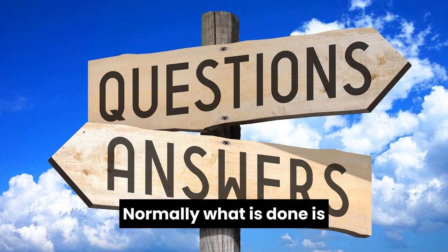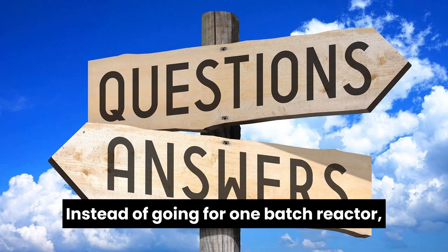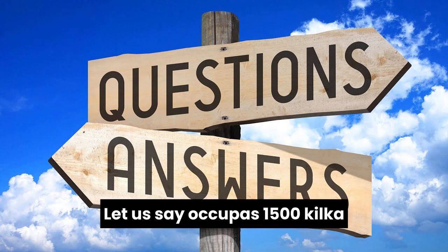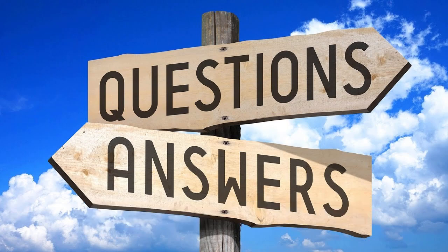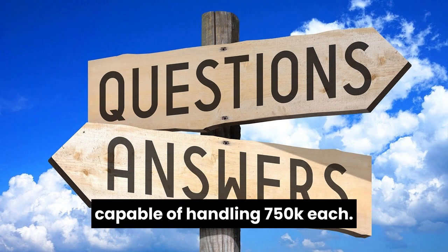Normally, what is done in large capacity STPs is that instead of going for one batch reactor, you have 2 parallel batch reactors. Let us say you have 1500 KL of wastewater per day to be treated. So instead of taking one reactor, you divide it into 2 parts. It's like having 2 STPs of 750 KL. So you will have a batch reactor capable of handling 750 KL each.